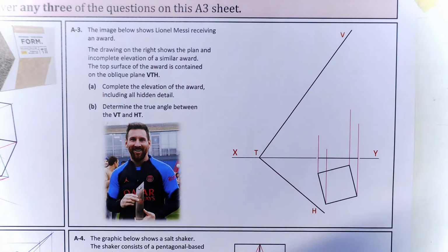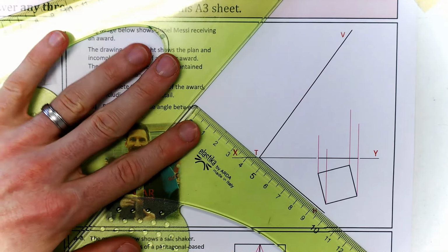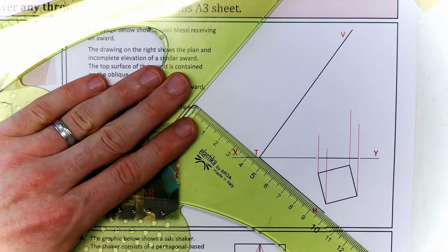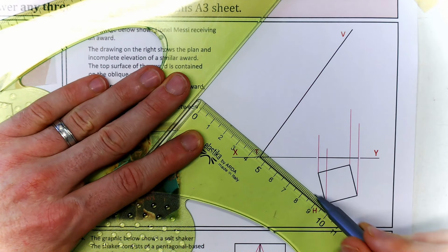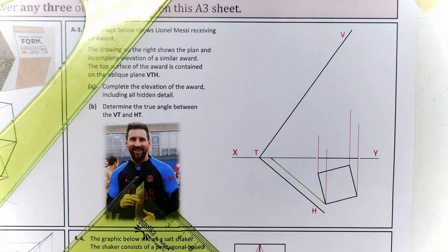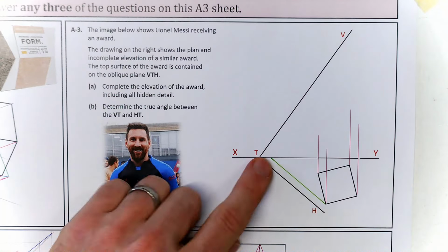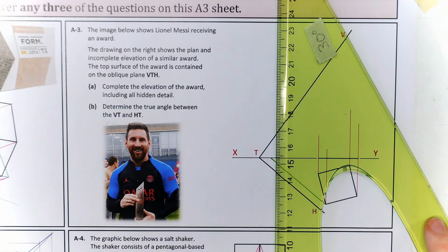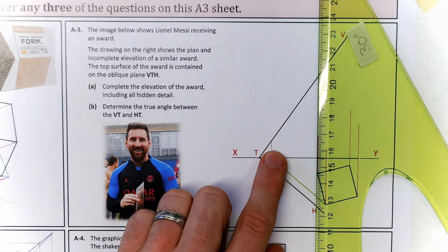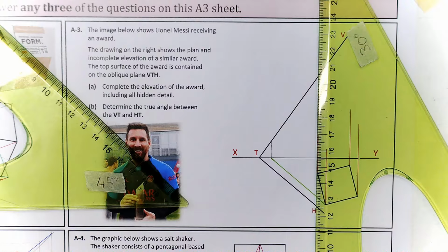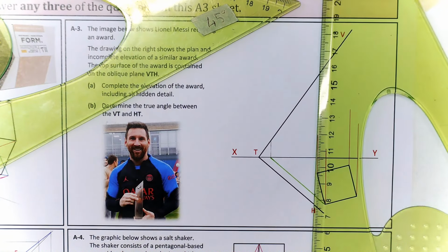So let's start here with a parallel line to my HT. That's going to give me a horizontal line. I'll just use a color now to indicate all of these. What's happening then is that is a point on the vertical plane, or on the VT. So let's bring that up. That's determining a height. It has already been projected up.